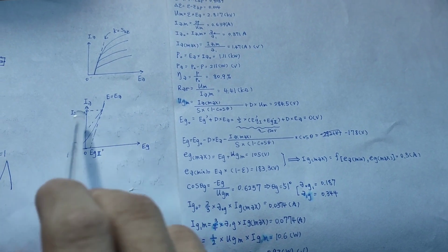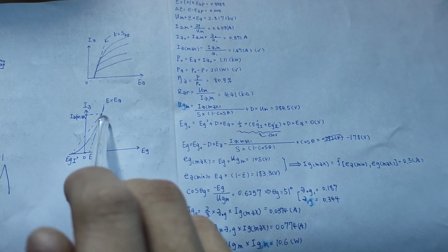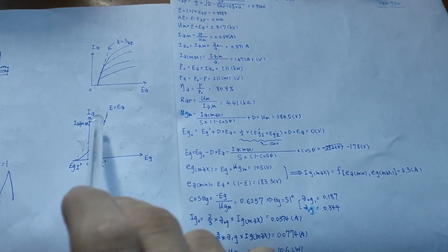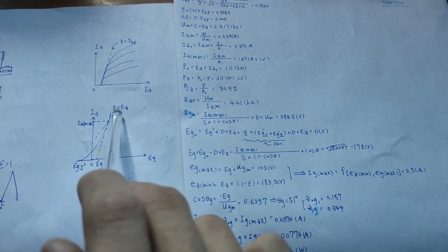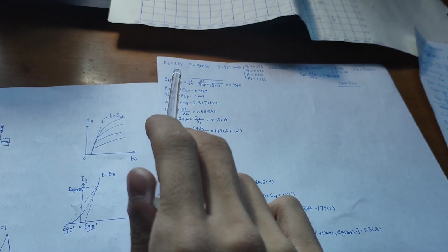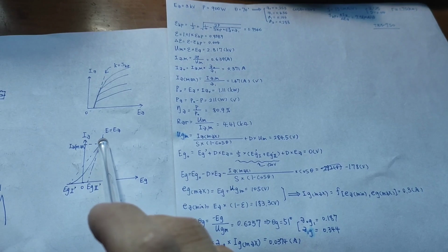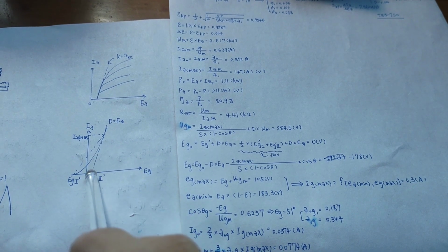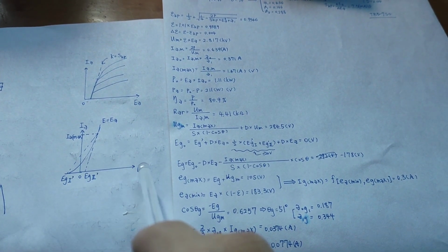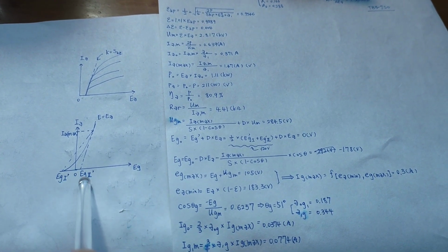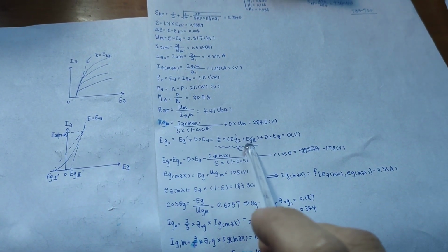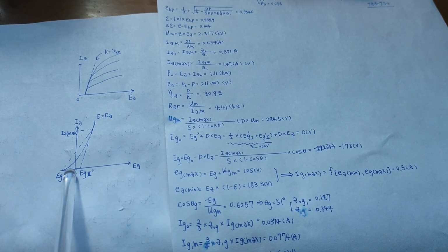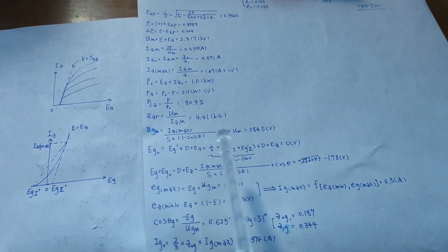which means that the point has the maximum anode current value in your calculation. Also, it is on this line, so the voltage is your rated voltage. And you need to draw a line which has the same K factor at this point and make a joint to the x-axis, and you will get the second value we needed in this equation. Normally, these two values are all negative. Remember that.